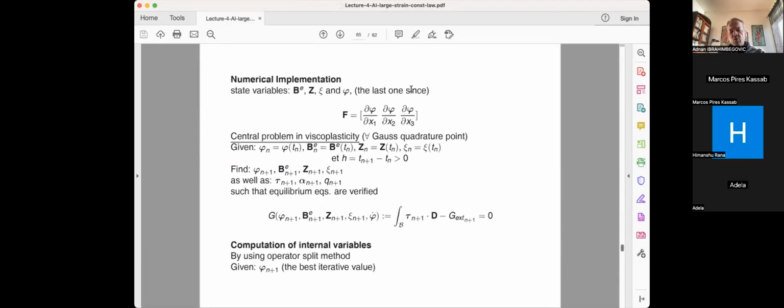So how you do this computation now? Well, you have certain number of variables to represent. You need to have like a global representation of your displacement field that allows you to recreate the deformed configuration by adding the nodal values of the coordinates and nodal values of this displacement to contribute to the position vector in the deformed configuration. Then you build your deformation gradient at any particular point you need it by taking the partial derivative with respect to coordinates x1, x2, and x3.